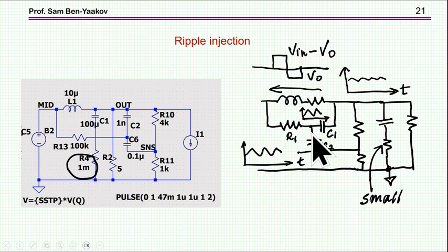And as you might know, this is actually the idea used to measure the inductor current without an additional sensor, just relying on the inductor and its internal resistance. Okay, this is a well-known technique. Here we are using it to generate just the ripple. We're interested in the ripple.